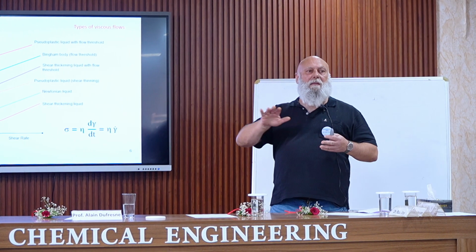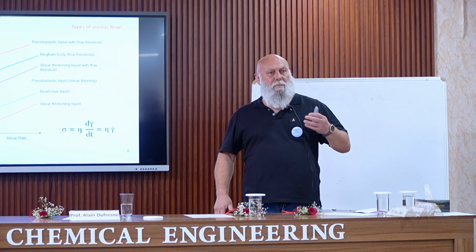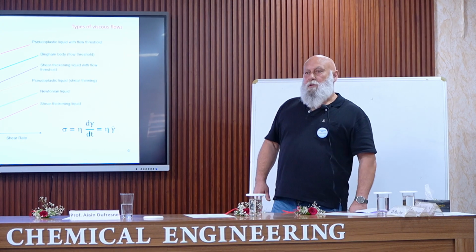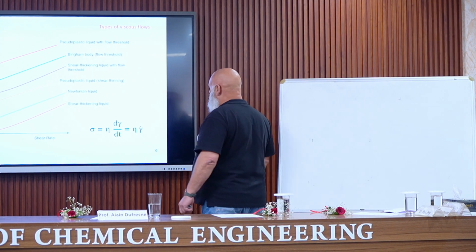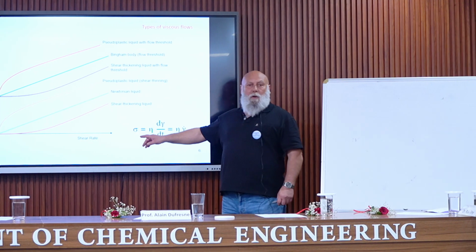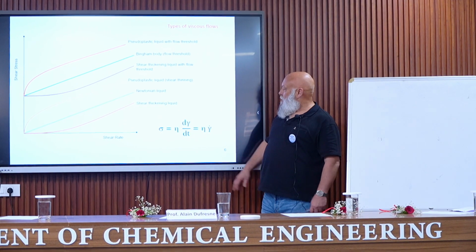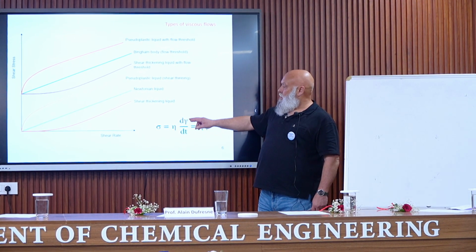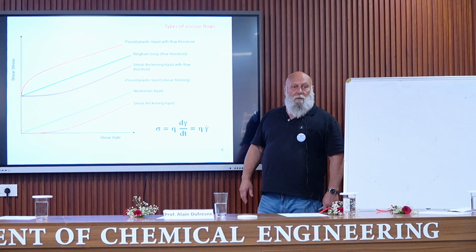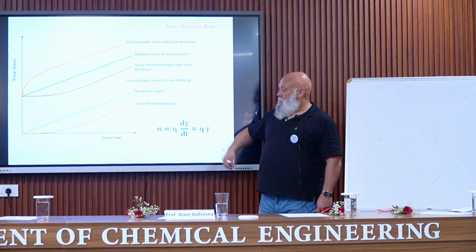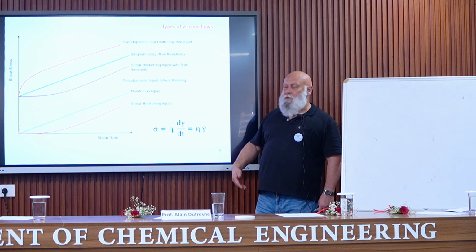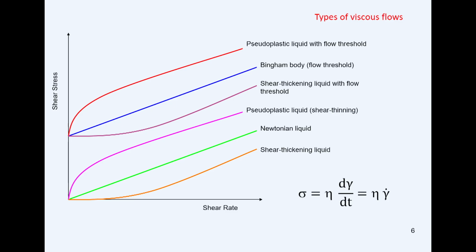And the consequence of this is that there is a linear relationship between the stress, which is applied to the material, and the shear rate. So gamma corresponds to the deformation, the strain, and the parameter that relates these two terms is the viscosity of the material.